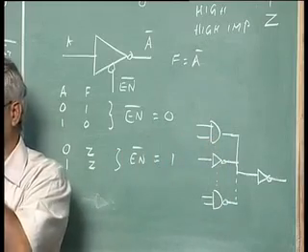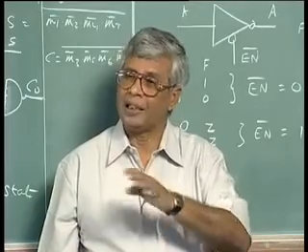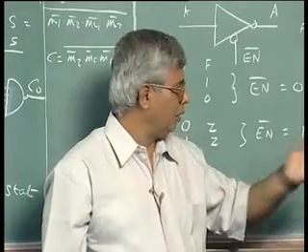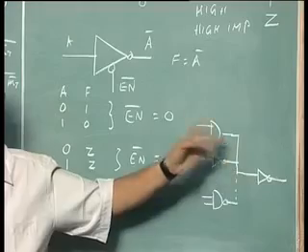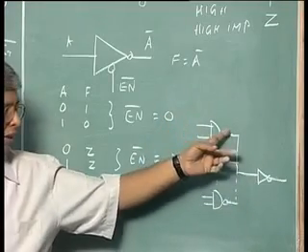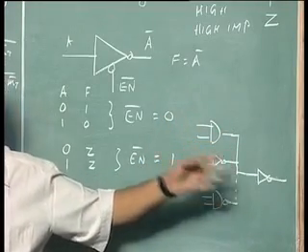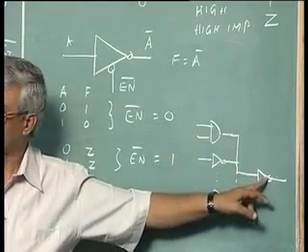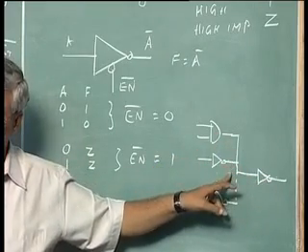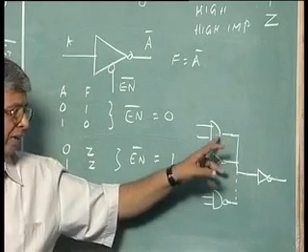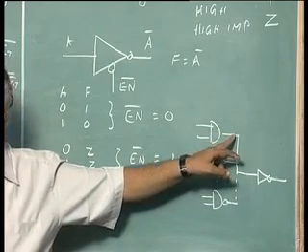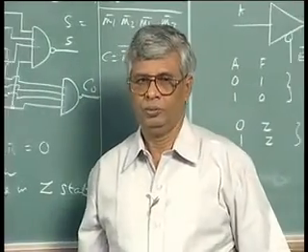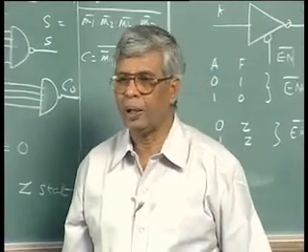As I said, that's not a good solution, not a practical solution. If I don't do that, what will happen is, whether this is high or low, all of them have to be high or low. If this is high and all of them are low, low is 0 volts, practically ground. So I am trying to push this high voltage into this, but at that time this is low and gets grounded. This also gets grounded. So whenever I am trying to pull this up using the output of this, because it is high, these two gates will pull it down to 0. Right? These are the problems.